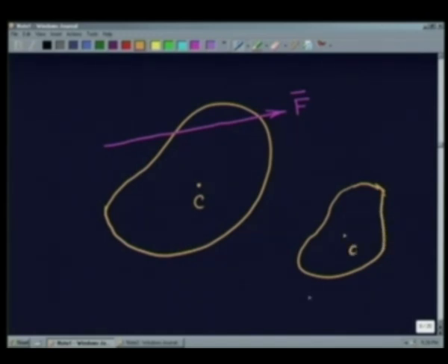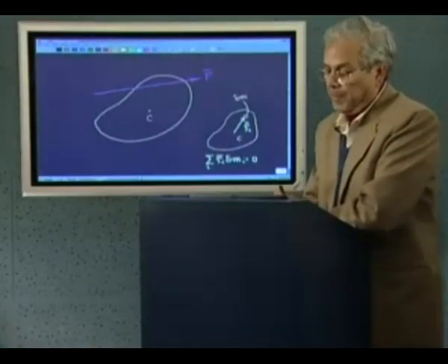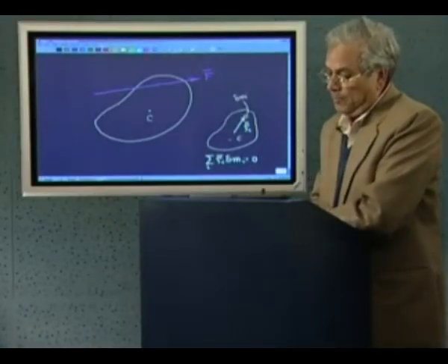This is C. So if you take any particle whose mass is delta m_i and which is located at a position rho_i, then if you sum up this product for all the particles, it will result in 0 if C is the center of mass. This you have to keep in mind. That is the definition of center of mass.